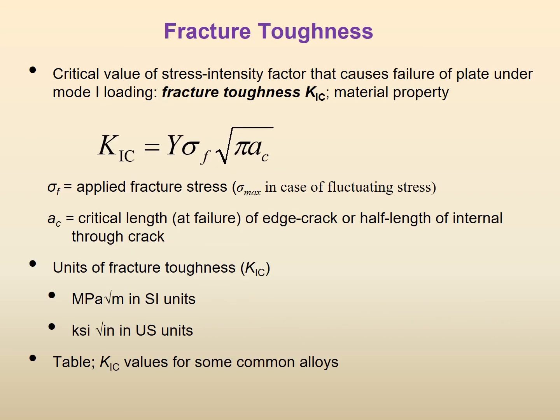So now, after this fracture mechanics equation, can you give a new definition of fracture toughness? Yes, it is the definition: the critical value of stress intensity factor is called the fracture toughness of the material, right? K1, without this C, was Y sigma root pi A. But is there a critical value of stress intensity? Critical value of stress intensity, right?